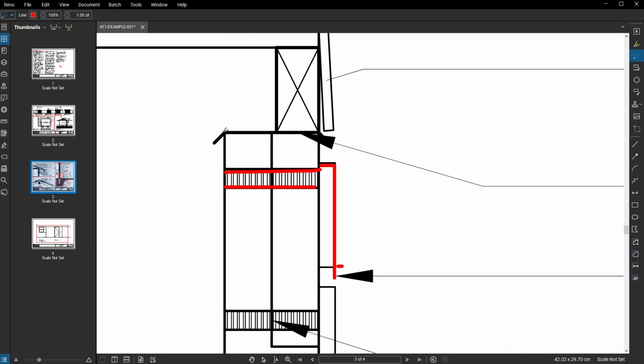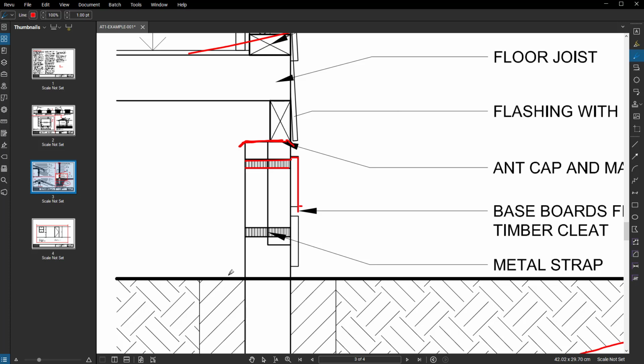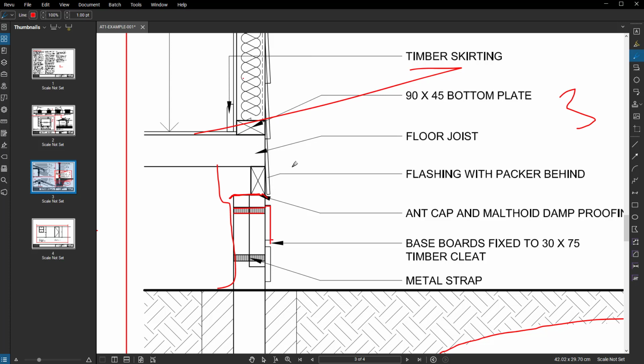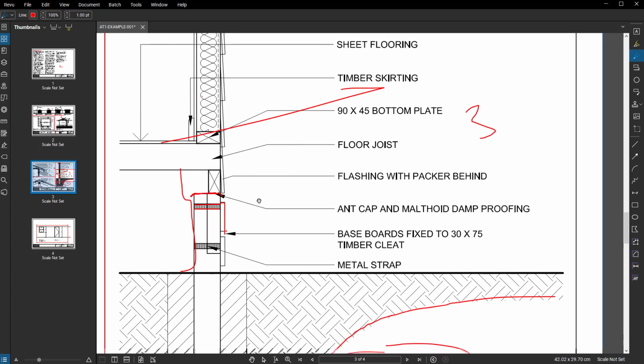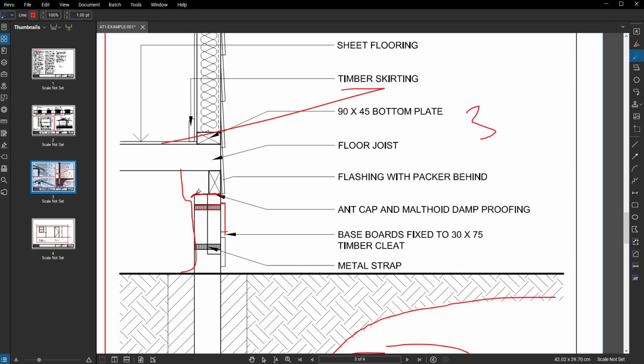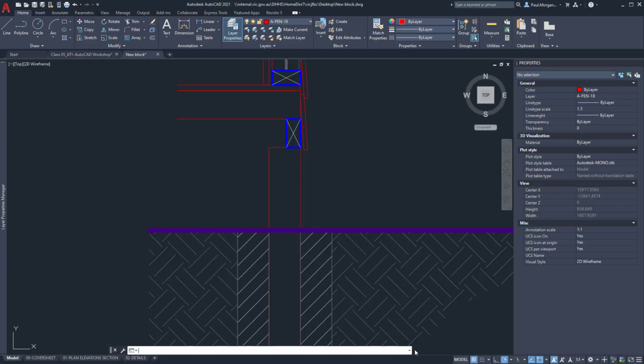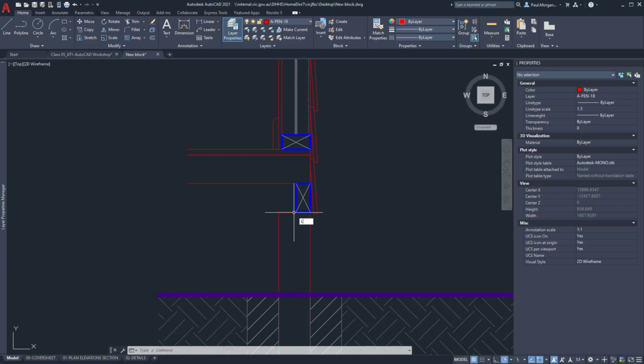And then you've got this thing here, which is an ant cap, which is essentially like a steel cap that goes on top of the pile to stop termites and ants from egressing into the building and rotting and eating the timber and other materials. So, which I think is covered in one of the Build Some videos that I linked in an earlier class wrap up.